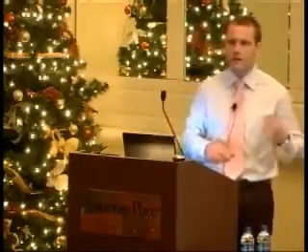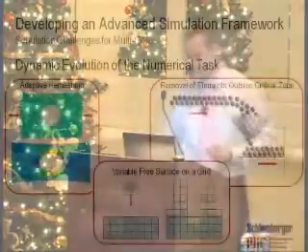Now, for the multi-core type architecture, you're dealing with a shared memory, so there's not that necessity to actually send out physical parts of the model to different machines. You can maintain a single memory source, and so what you could actually do is something like this domain distribution, where each of the calculation points, in this case elements, rather than having to be clumped together, a core can just calculate on that single point as it becomes available to do so. And if you can program that correctly, then you're dealing with an events-based load balance, which is far more superior with respect to processor utilisation.